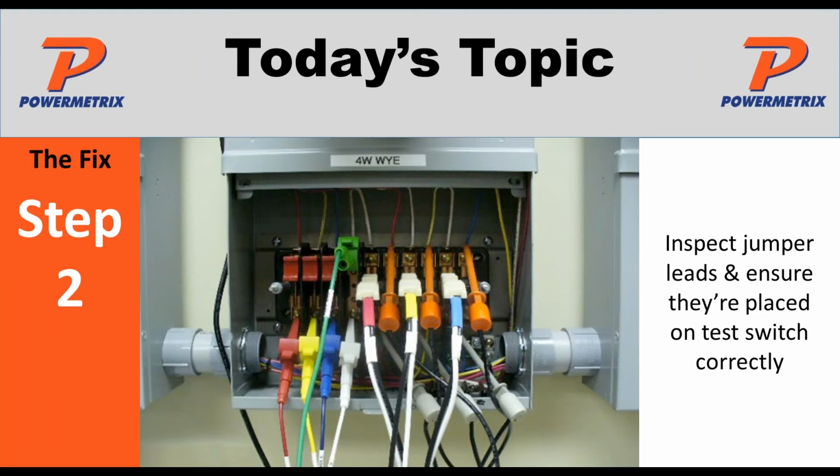Inspect jumper leads and ensure they're placed on the test switch correctly. And again, we've actually hooked this up. That is the proper way to hook those jumper leads up. They don't stack on top of each other or anything like that, but it doesn't matter if orange is on top or gray is on top, whatever, but make sure that you are at the very bottom of the test switch, which is the duckbill there.